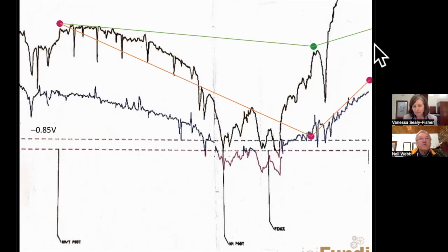Yes, for sure. I mean, you can see that this level of protection falls off almost instantaneously from a distance point of view. In the ideal world, if the pipeline was uniformly protected and the wrapping was in uniform condition and was sitting in uniform soil, you can say that the test post reading is representative. But if you don't know that, then the test post reading represents 3 meters of pipe adjacent to the test post. And you can see that you just go here and 3 meters away, there is no protection at all. It is possible. It's definitely sobering, isn't it?